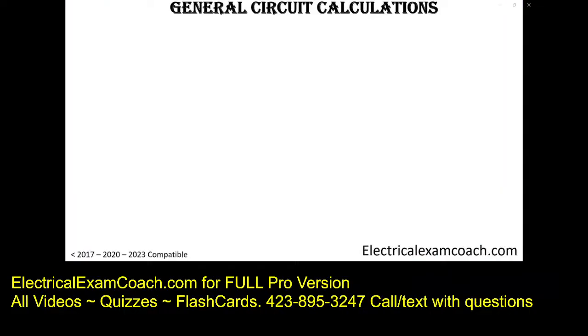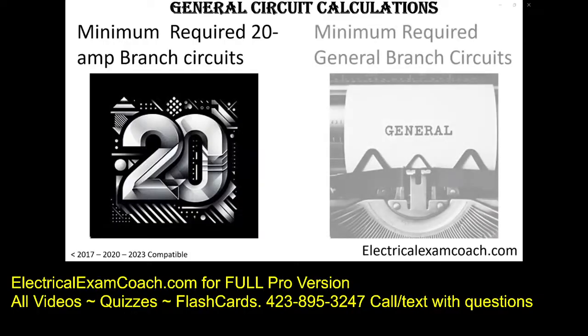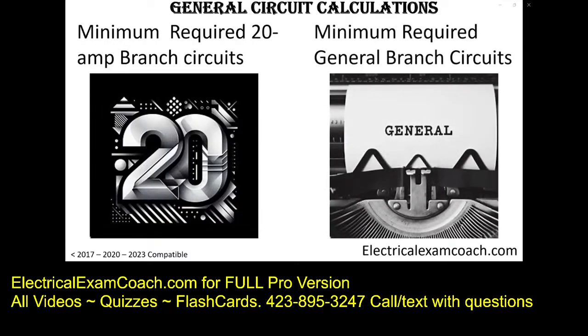In this video, we're going to cover how to calculate your general circuit calculations. Now, these type questions fall into 2 different scenarios. One, they're going to ask you the minimum required 20 amp branch circuits. And then the other one that looks almost identical is when they ask you the minimum required general branch circuits for a specific size home. We're going to look at these piece by piece, and we're going to break them down one at a time.